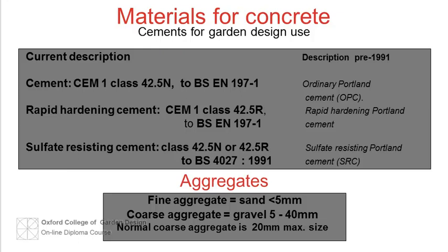In the past, concrete was often specified using nominal proportions. That is to say, the required volumes of cement, sand and coarse aggregate were quoted as a ratio, such as 1 to 2 to 4. This meant in practice that for each shovelful of cement there would be 2 shovelfuls of sand and 4 of coarse aggregate. Unfortunately, a shovelful of wet cohesive sand is very different in volume from a shovelful of dry, free-flowing cement powder.